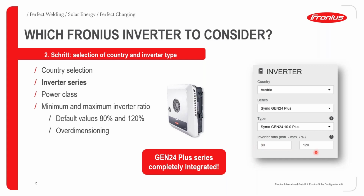The maximum limit is set to 120%, and if you do a calculation, 120% of 10 kilowatts would give us 12 kilowatts. So the range of suggestions that I'm looking for is from 8 kilowatts to 12 kilowatts in this example. So basically, when I click the search bar, it will give me all applicable scenarios whereby I have at least 8 kilowatts worth of PV modules and a maximum of 12 kilowatts worth of PV modules.